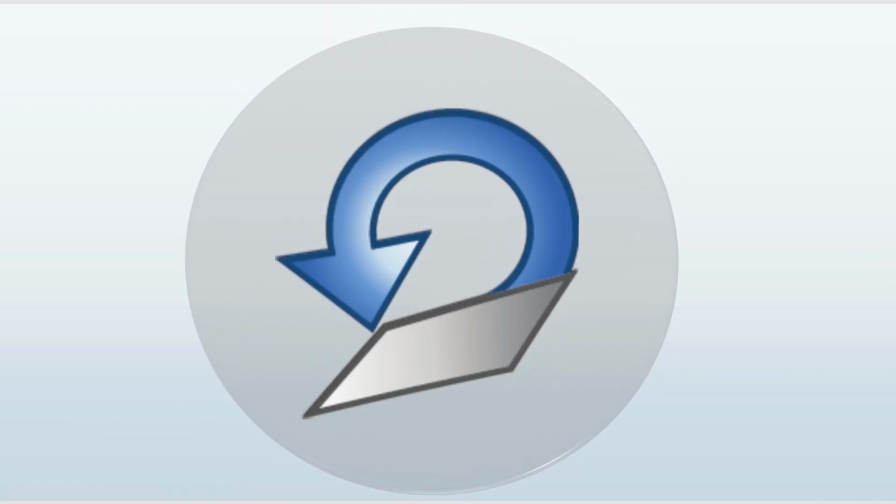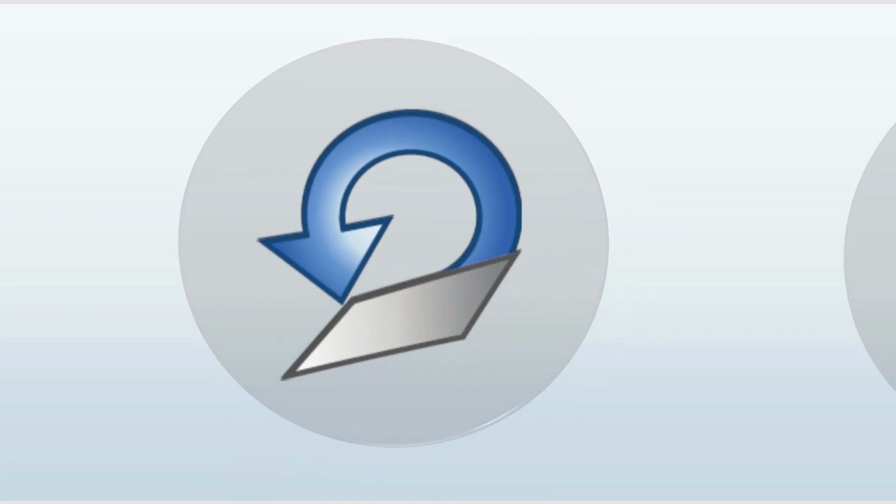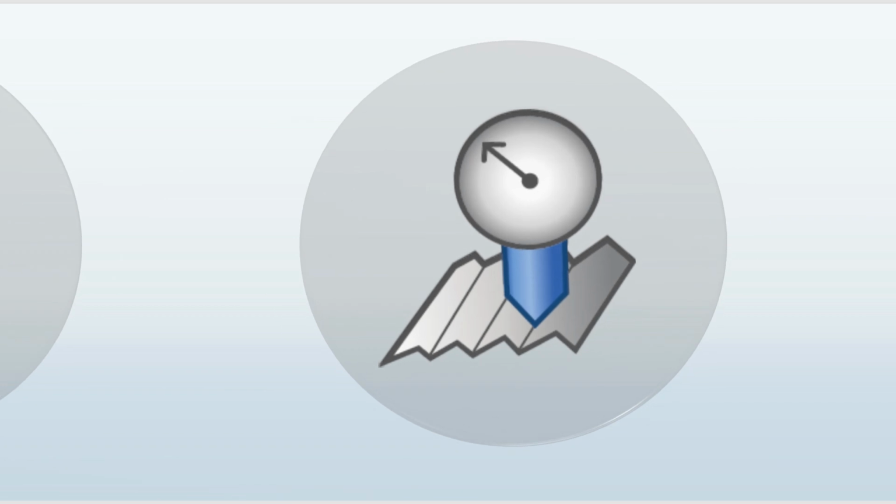First, turning processing material. Select this action if you require the execution of the processing steps to be stopped so that the processing material can be turned over. Then we have surface compensation. This action carries out surface compensation of the processing material in relation to the relative processing of the objects. The number of and distance between the scanning points can be adjusted. The size of the area to be scanned is defined by the job borders.